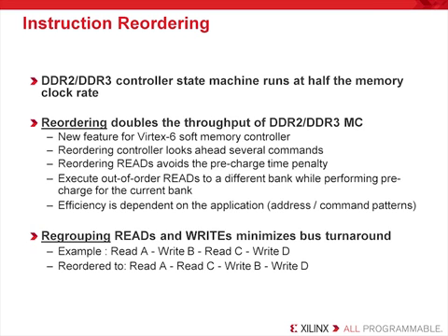Likewise, the state machine to process the commands can be run at half the frequency of the memory system. This makes meeting your timing needs significantly easier. For example, a 500 MHz based memory system needs only a 250 MHz controller state machine. This allows us to build controllers in lower speed grade devices at higher frequency than we could have done with a full frequency memory controller.